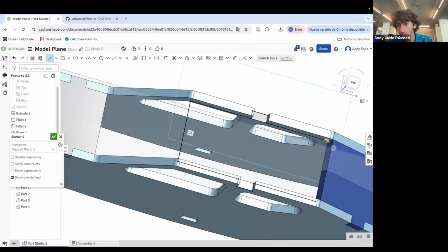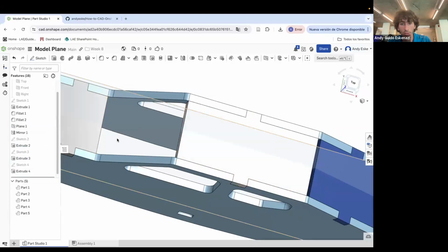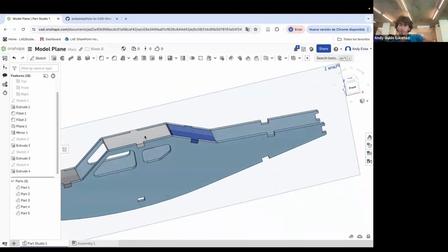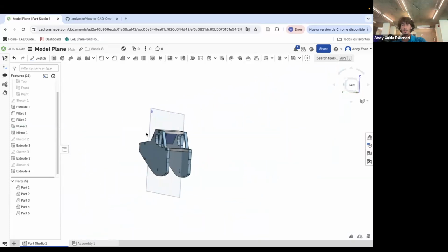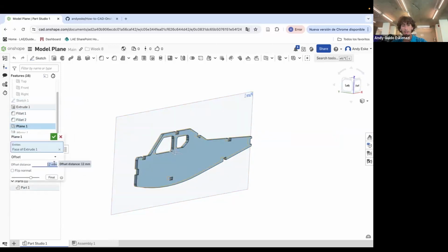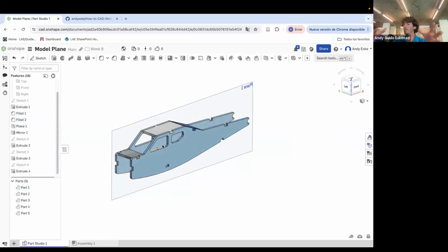There we go. That's new. Perfect. So you see now I have a roof in there. Now, because of all of the dimensions, right? The way that we did this, say we look at the airplane and we realize I want this to be slightly wider. Then I can always go back to plane one, edit here, and make it say 13. And everything that we've done will automatically change. So this is a very nice approach.